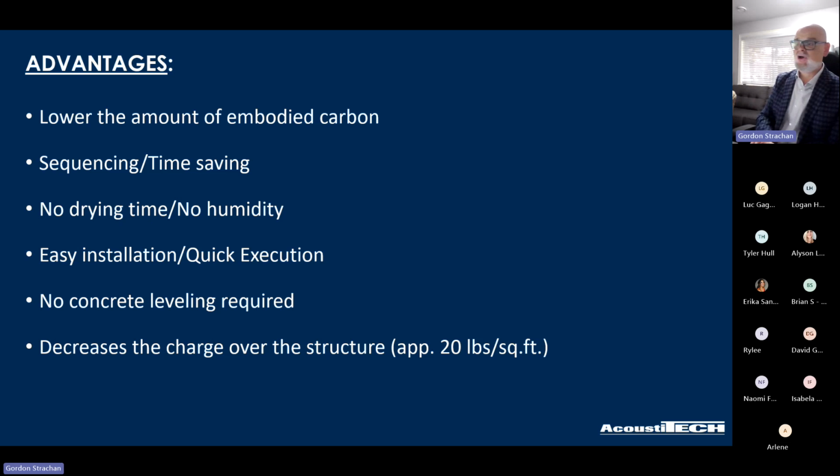Sequencing, big. When we're talking about drying time, sequencing with concrete can take a huge amount of time. If you're using an engineered wood or real hardwood floor, you can't put that down until the humidity levels drop to 8% per 100 square feet. With concrete topping, that takes a very long time. It can be longer than the typical 28-day drying time, even. So these are important factors. Humidity, a lot of the time you can end up having to deal with humidity on site when you're drying your concrete or Dri-Crete.